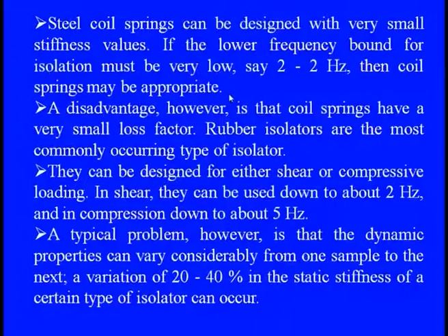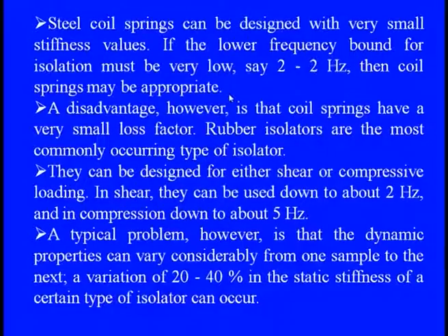In shear, these can be used even below 2 hertz, and in compression up to 5 hertz. Even for the dynamic properties, which vary accordingly, there is a variation of 20 to 40% from the static stiffness with the isolators.